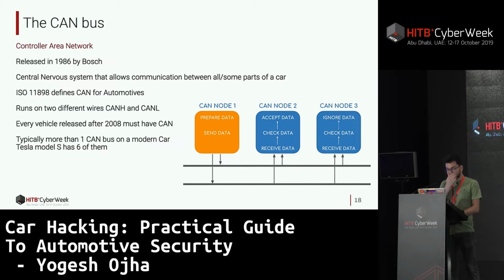In CAN bus, there are just 2 physical wires that connect the dashboard to the engine to the steering, and all this sort of stuff. The CAN bus protocol allows ECUs to communicate with each other without complex dedicated wiring in between. Suppose any day you wanted to put some new component in your car, you don't have to worry about inventing a new bus. You can just implement it on top of the CAN bus.